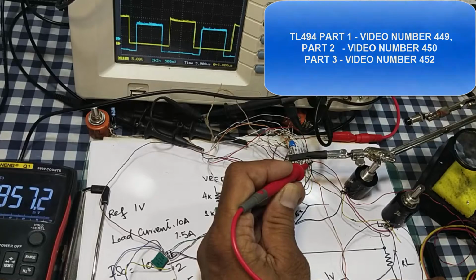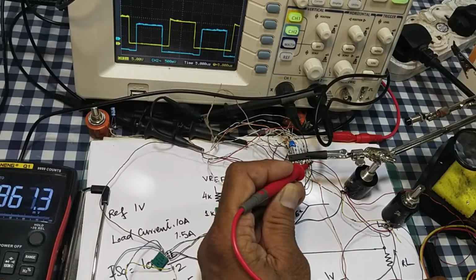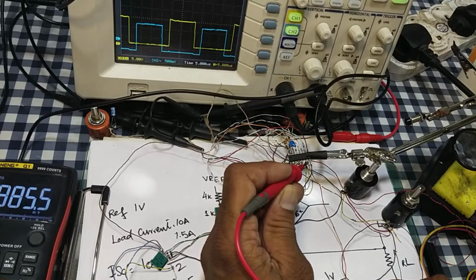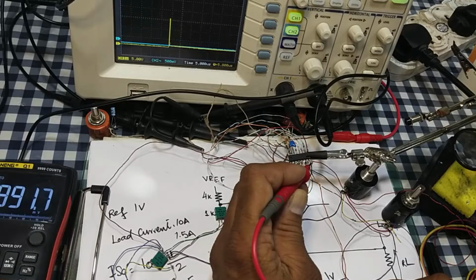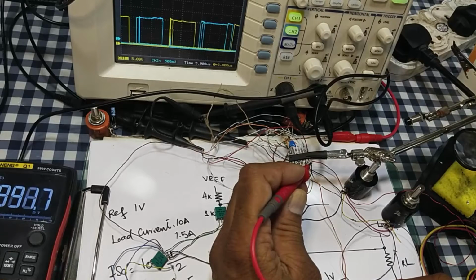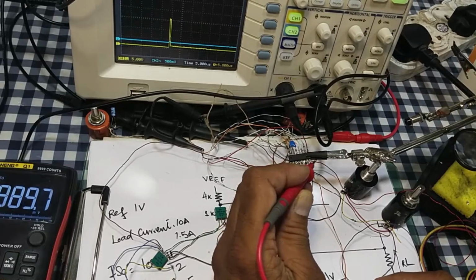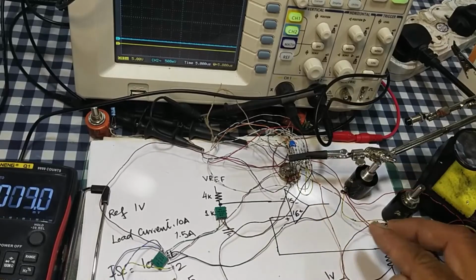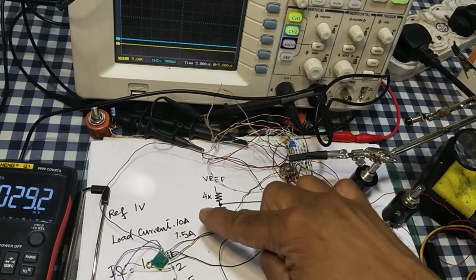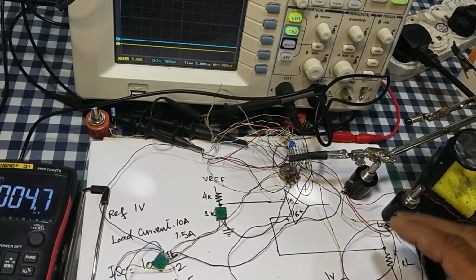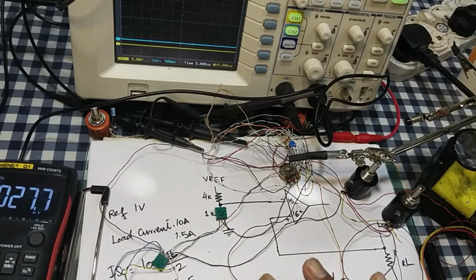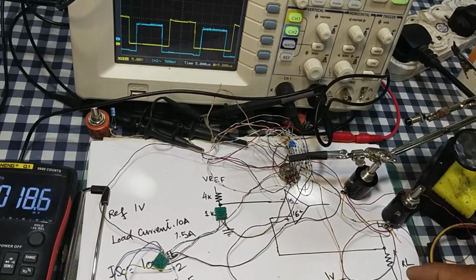When the voltage increases beyond the rated value at the error amplifier input pin, when the current sense feedback increases or becomes equal, this IC will cut off its switching to protect from overcurrent. We will calculate and arrange this practical circuit to monitor this function.